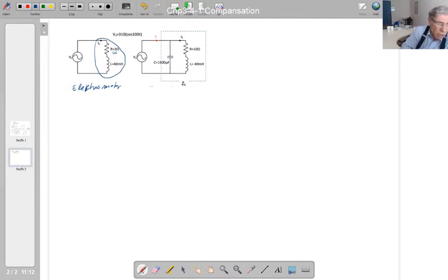That power is going to be the average power, P average. We are going to calculate this, and then we are going to calculate the reactive power as well. So we know the average power is 1/2 Vm Im cos(theta V minus theta I), where Vm is the maximum value of the voltage and Im is the maximum value of the current. So this is the phase difference between voltage and current. What we mean is this is our motor. The voltage here, this voltage angle is theta V. And the current consumed by the motor, this current angle is theta I. So the phase difference between those two, voltage and current of this motor,